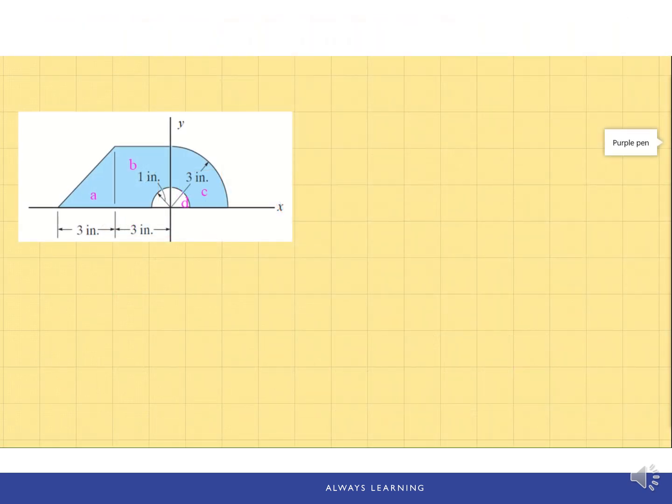So we're gonna make a table again, but before we make the table, let's write down the formulas that we're gonna use as a guideline to see what values we should put into the table. So we're looking for the centroid of this composite area. So x bar will be equal to the sum of x tilde A, the area of each segment, over the sum of the area.